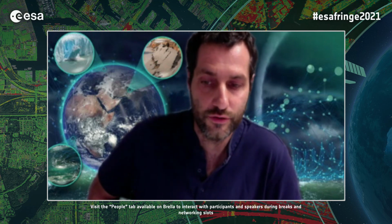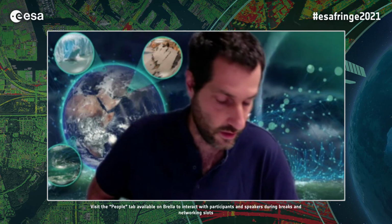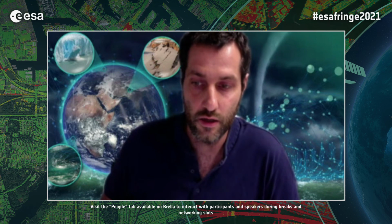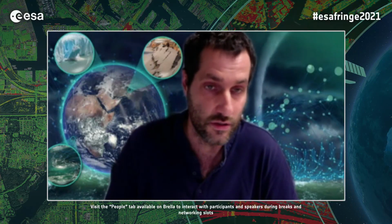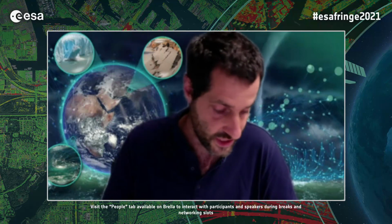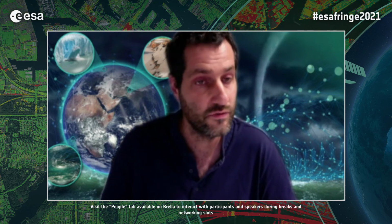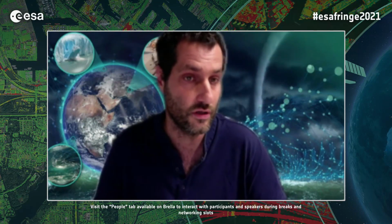There is one question from Rudy Vindliber: with such a huge amount of data, how do you check velocity product quality, decorrelation, phase unwrapping errors, calibration, and accuracy before matching everything together? All the velocity or the unwrapped phase are calibrated against the speckle tracking map. This speckle tracking map has been constructed using a region where there is no motion as calibration, and long tracks that cover from coast to coast, for example from Envisat ASAR. So there could be some issues: if the speckle tracking map has biases, then they would be reported in the phase map. We checked the results against GPS measurements when available, and it shows that the phase map was much better than the tracking map. But obviously, if we had more ground control points, it would definitely prove very useful to do a better calibration over Antarctica for sure.